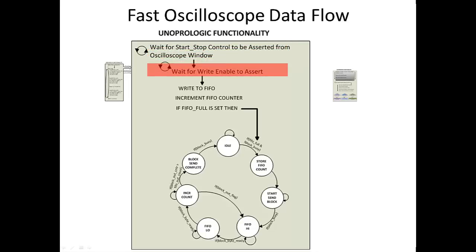When the write enable from the Arduino asserts, it causes the block of code that writes bytes into the local FIFO, the Arduino logic, to read the data on ports B and C, then clock that byte into the FIFO. This process continues until the internal FIFO count reaches 8 bytes. When this happens, the FIFO full flag is set.